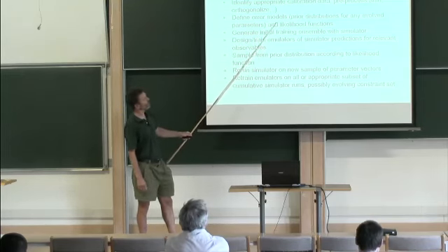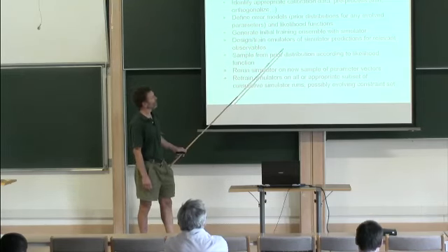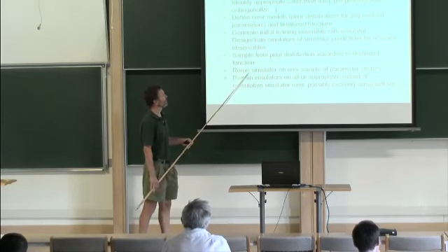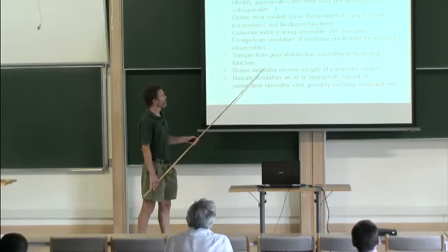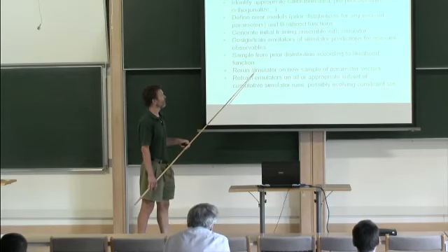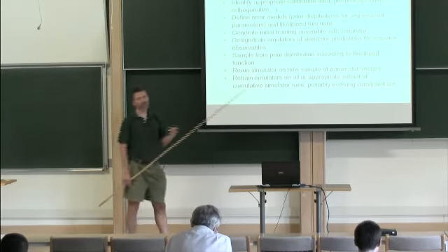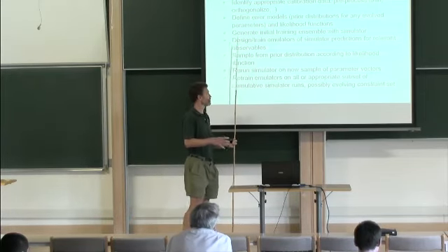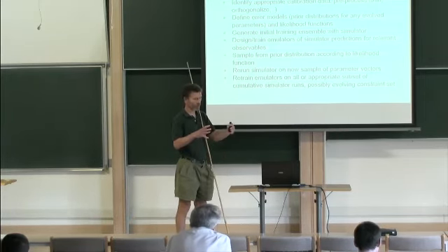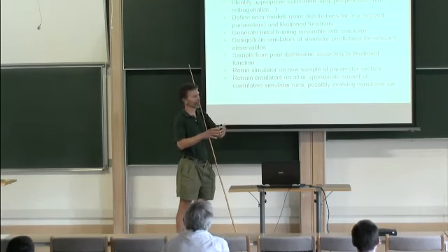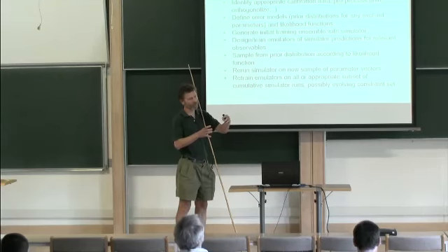Error models, I've already mentioned, are a big challenge. Then you have to generate initial training ensembles with the full simulator, design your emulators, do some kind of sampling, this whole framework, Markov chain Monte Carlo. And then you have to do this iteratively. If you do it once, you come up with a distribution based on the emulators, a reasonably high probability set of parameter vectors. You actually run your simulator with those new parameter vectors, and you'll find out that there were errors, so you've got not as high a probability as you wanted.